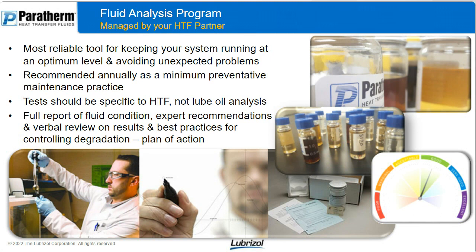There's a lot of gray area when you're condemning a thermal fluid. It depends on the temperatures that you're running, the cycles you're running, how long the fluid's been in there, what it looked like 3 years ago versus what it looked like last year to this year. A lot of stuff can happen in that time period. So you want a verbal review on your results, maybe we'll talk to the experts, and then consider the best practices for either controlling the degradation or removing the fluid. You need a plan of action, and you need to be able to work with a reputable supplier for that.